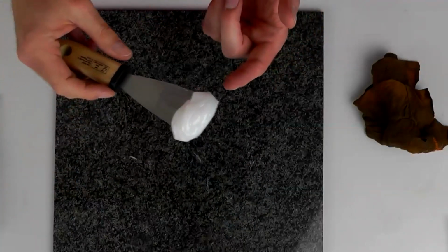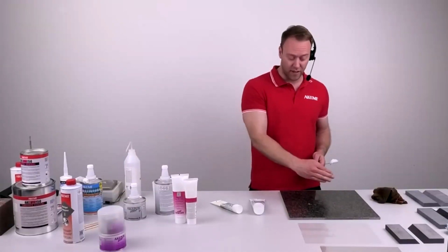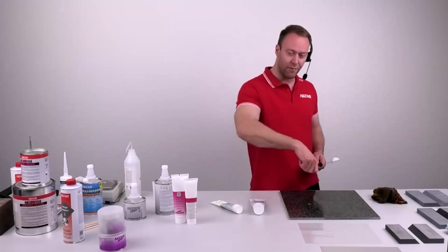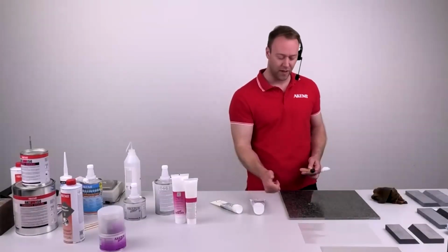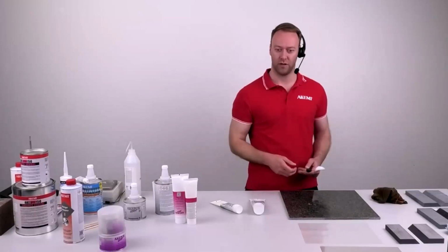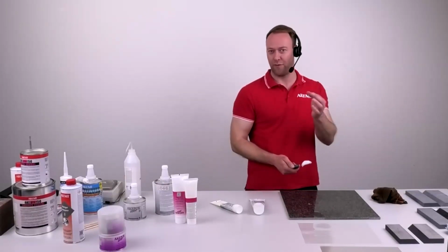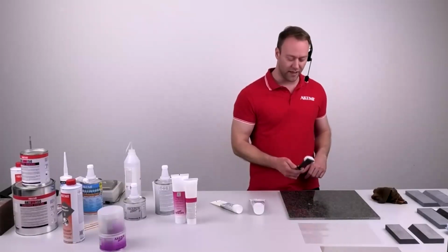So here what you can do is you make your 2 lines or 3 lines. Then you put the A component aside and mix the color into it until your color is a good match. Then you add the B component to adapt it. With a color concentrate, it works because you have only 1% color concentrate. It does not upset your mixing ratio.